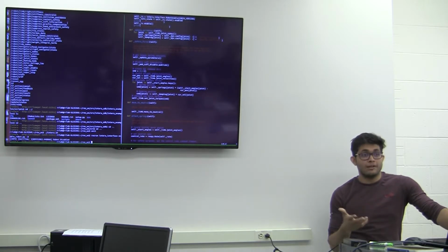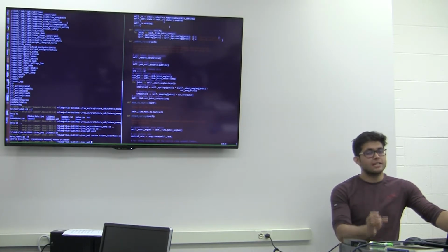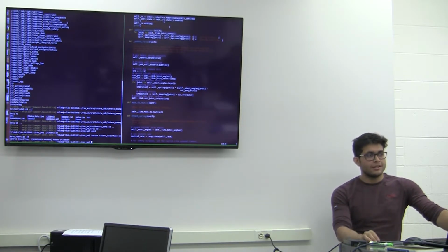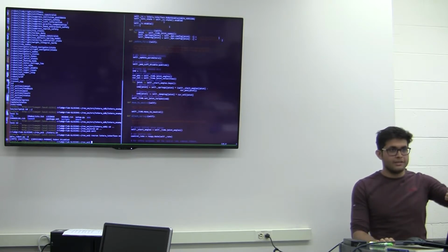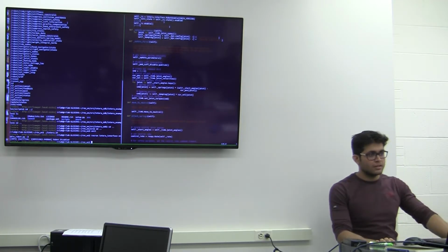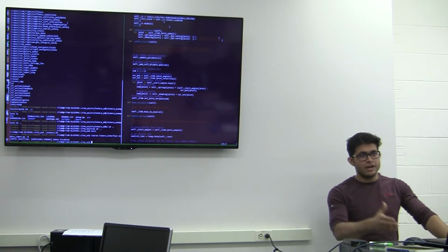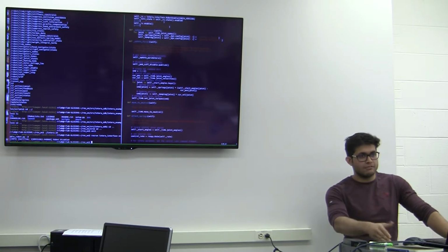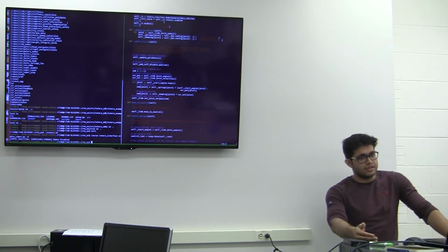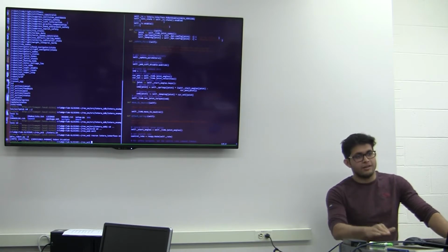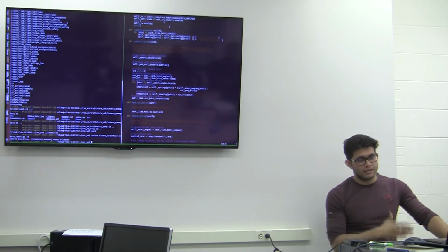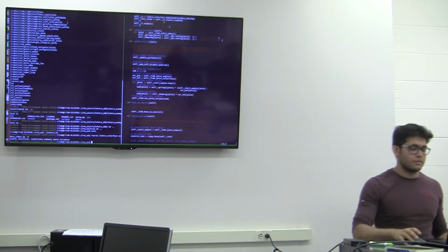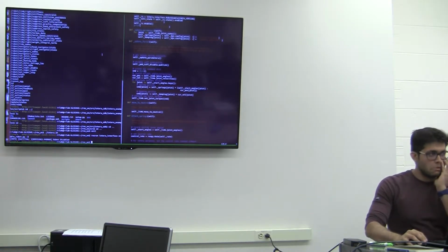Before running any command or script, test each part of that script. Test each command. Let's say you want to open the gripper: test outside how you open and close the gripper. Don't enable it in the script and run the script first. Just test, okay, this is the API, this is the service, how do I call that service outside? Run it outside, then run it inside the script. Scripts run in one go. Outside you can always control the phases.